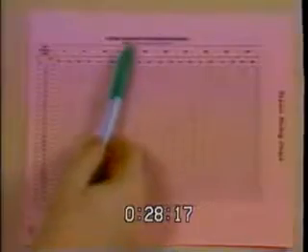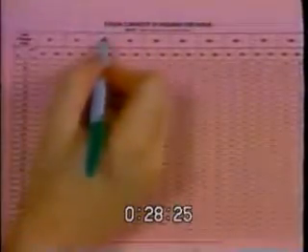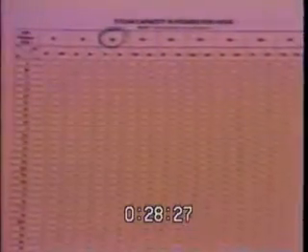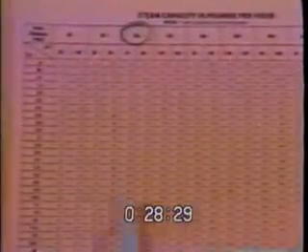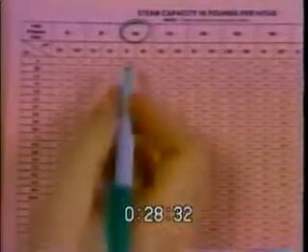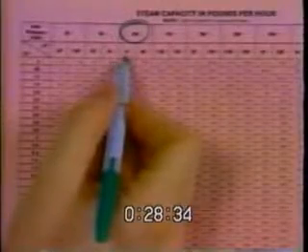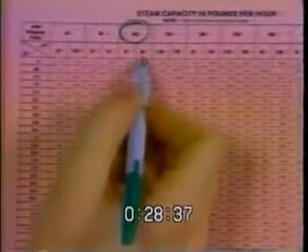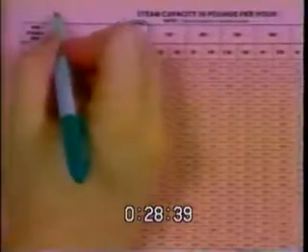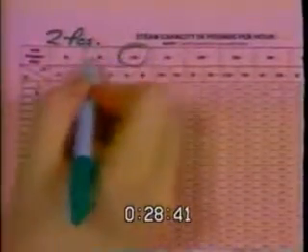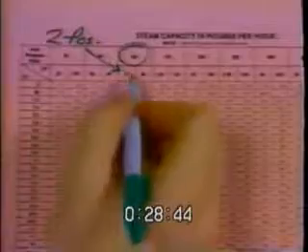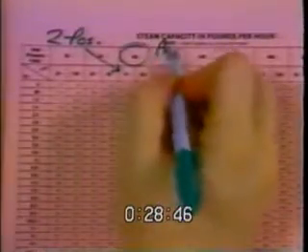Here's the last method for finding the CV for a steam valve. Let's take a look at it. That's the chart method. Notice at the top we have our inlet pressure. We are going to take the inlet pressure of 10. Now that column here is subdivided into 2 columns. Here it says 1 on one side of it and 8 on the other. The 1, or the one on the left, stands for 2 positioning. The one on the right stands for proportional control.